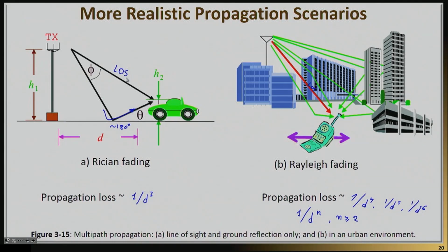Of course, in real life, the propagation scenario is far more complicated than what I make it appear here, in the sense that you have fading that changes over time, and you have to account for all of these issues. But as far as a system engineer is concerned, most of the times they will basically make this type of an assumption to at least have a reasonable idea of how much power they have to transmit in order to close the link.